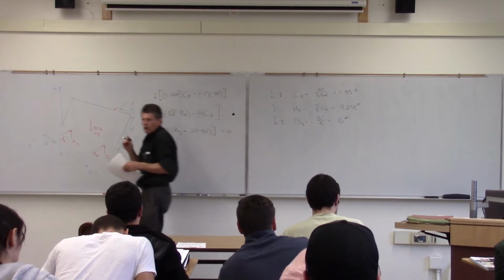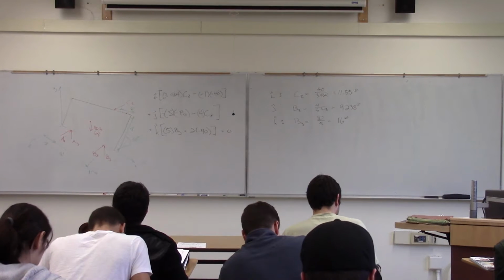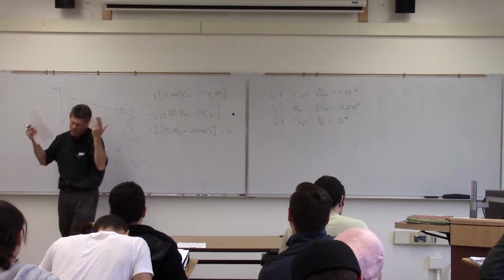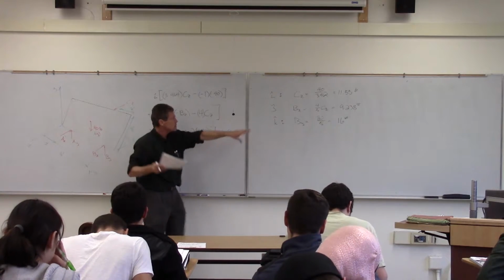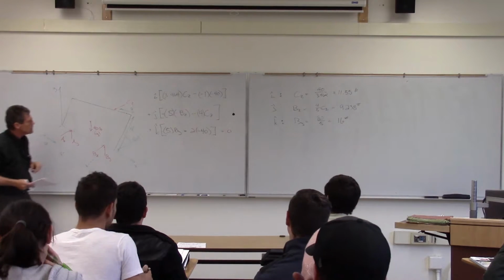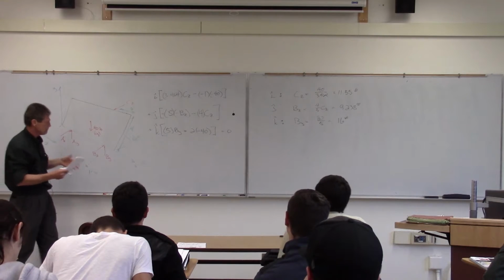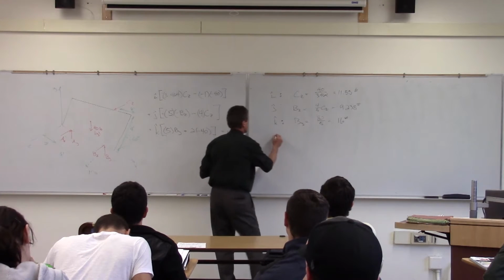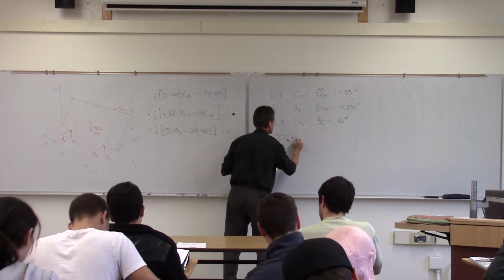So with our moment equation, we've already gotten rid of 3 things. Now, that may not always be the case. We might end up with situations where we have simultaneous equations to solve. You know how to do those, substitution and that sort of thing. Okay, so now getting back to the young gentleman's point, do I need to do a moment from now? Well, no. All I'm missing is AX and AY, right? AZ. So that's just CZ, BZ. So what we can do at this point in time is just do sum of forces in the Z direction.